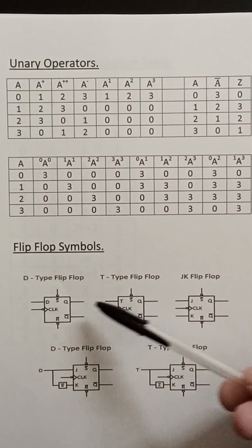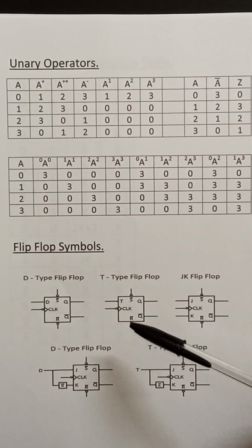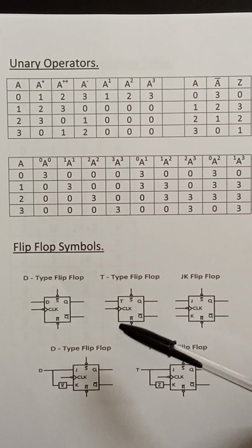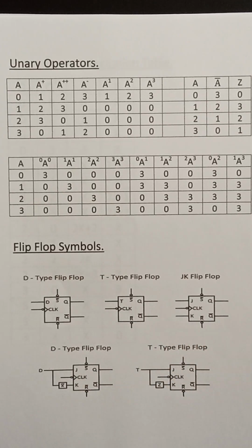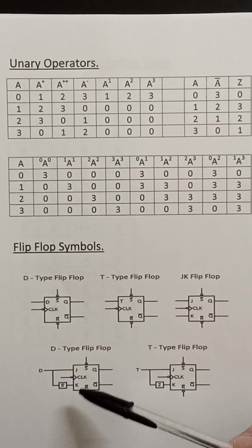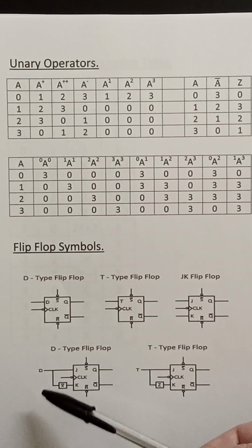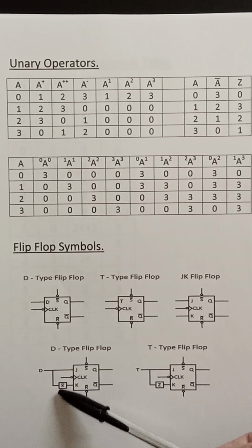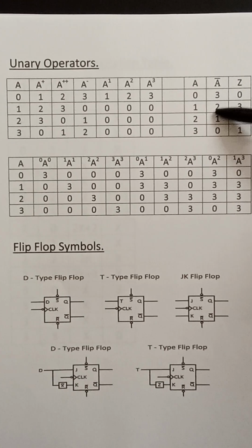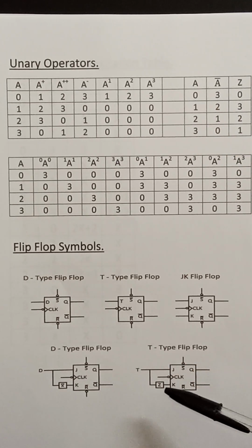All these clocks here are negative edge triggered, from a quaternary logic 1 to a quaternary logic 0. So here you can make a D flip-flop from a JK flip-flop by adding this gate in here. This is not X, this operator here. And for the T-type flip-flop, you introduce the Z function to K. Z is here, which is 3 times A modulo 4.